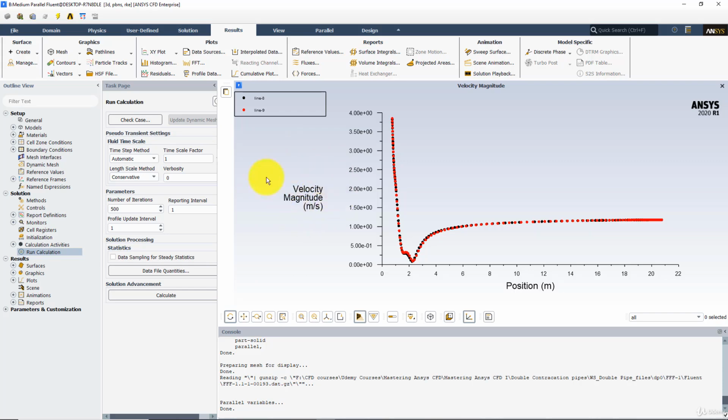in fact this is inside the Workbench. So with the combination of Ansys meshing, where we refine the mesh, and then we run the case in Fluent, and then we get the results and compare them in two different ways. One is for some integral quantity, and second is on the local quantities along some lines. And this can be done for any case you encounter in the CFD field.